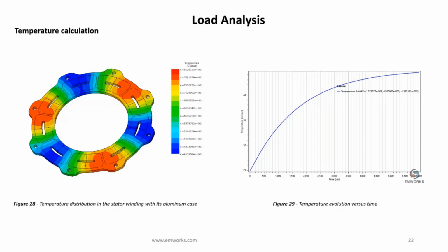Some axial flux machines have a design challenge related to their cooling system because the windings are located deep inside the machine, which makes their cooling more difficult than in a radial flux machine. EMS can help to solve this design issue using its thermal coupling capability. It is fully integrated within the same environment, as we will see later.